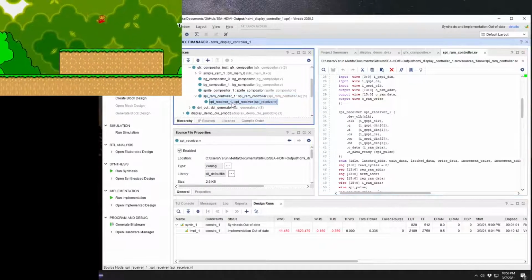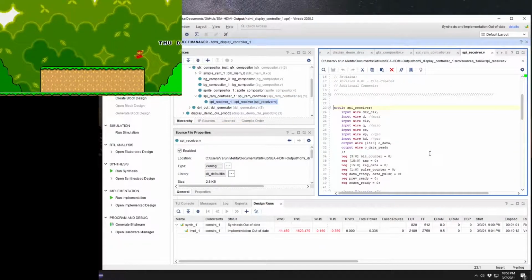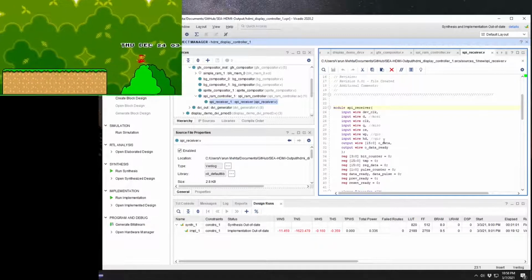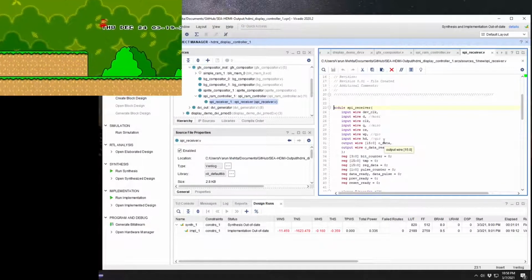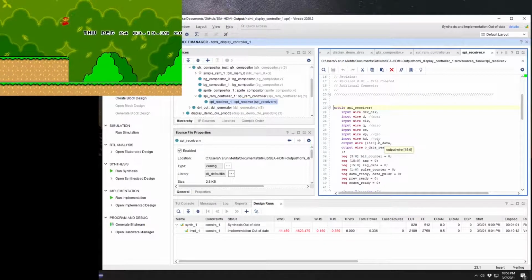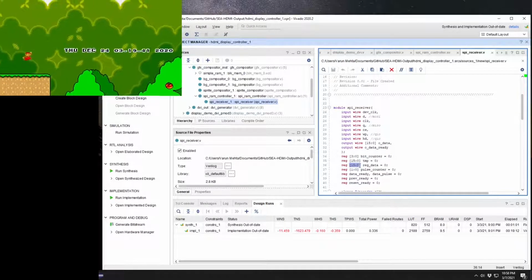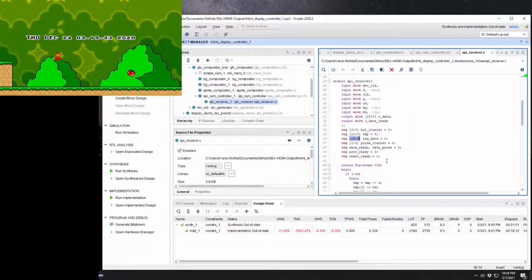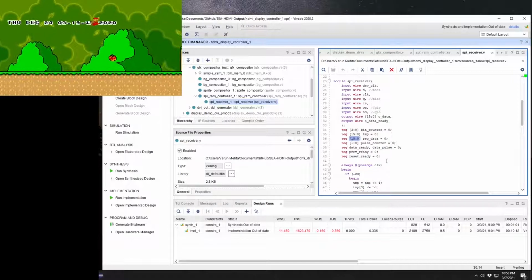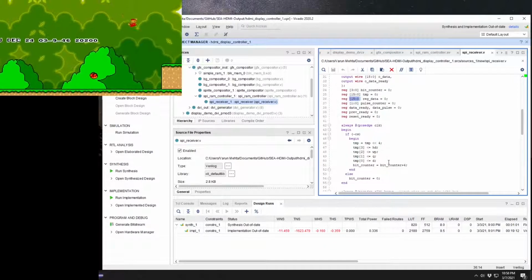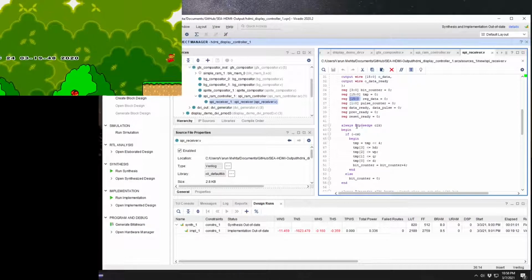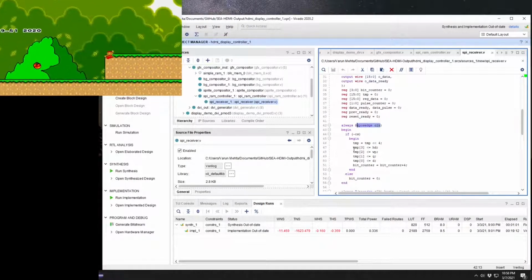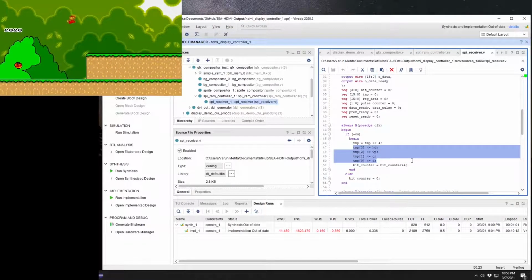So the SPI receiver is actually the piece that receives data directly from the ESP32 itself. The SPI receiver has no concept of addresses or anything. All it really does is it pulses every time it receives 16 bits of data, and we let our controller figure out where that data should go, what the meaning of that data is. So this is pretty simple. It's driven by the clock of the SPI bus itself, and just keeps shifting in 4 bits at a time.